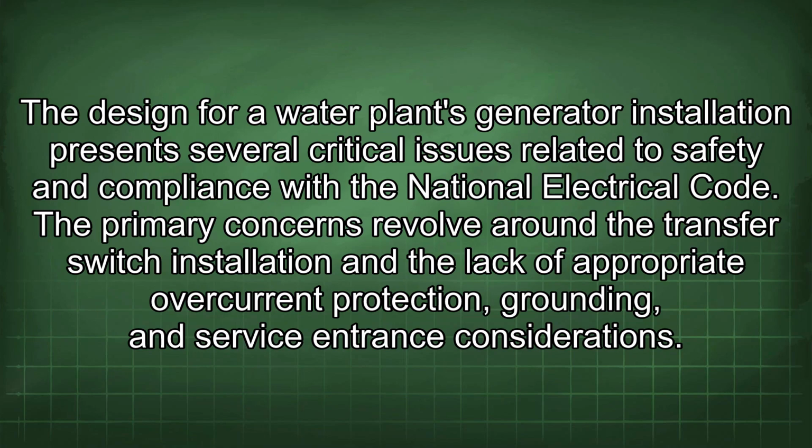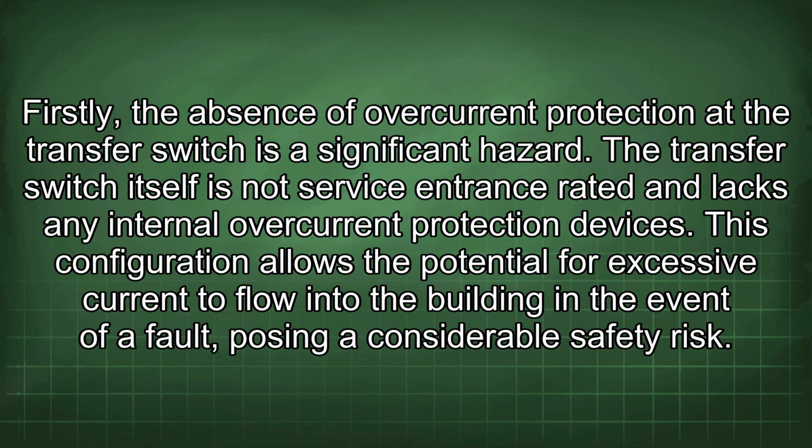The design for a water plant's generator installation presents several critical issues related to safety and compliance with the National Electrical Code. The primary concerns revolve around the transfer switch installation and the lack of appropriate overcurrent protection, grounding, and service entrance considerations. Firstly, the absence of overcurrent protection at the transfer switch is a significant hazard.